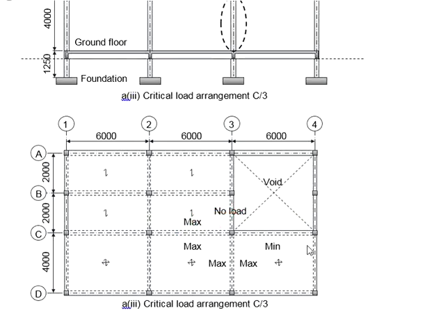As for the two-way slab, this shall be the load distributions. There will be loads acting on this side and also this side. Same goes here. By looking at the key plan here, you want to generate the largest moment possible.